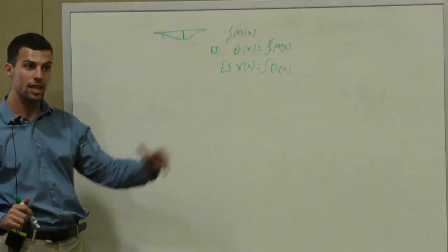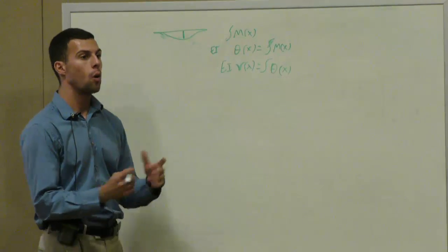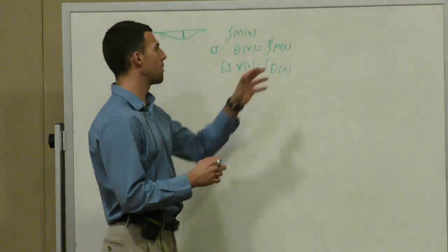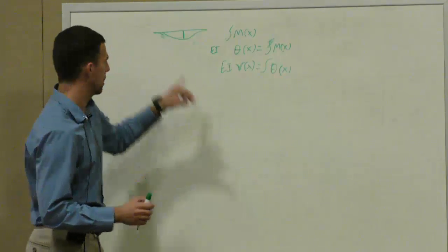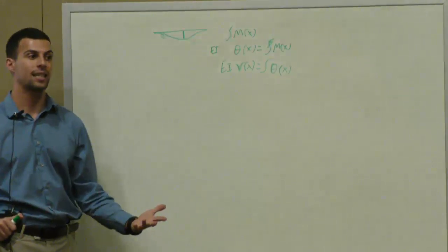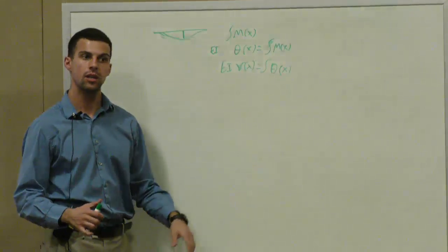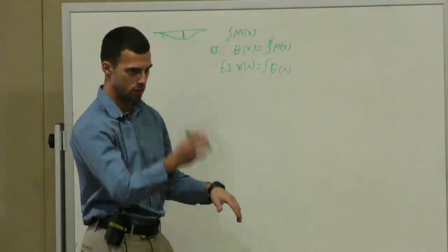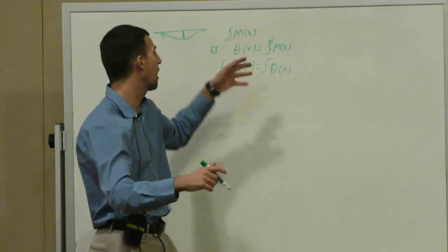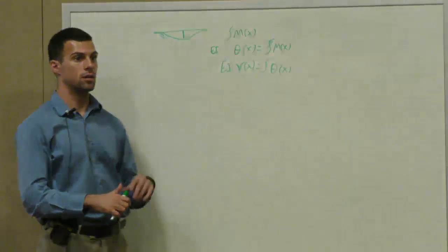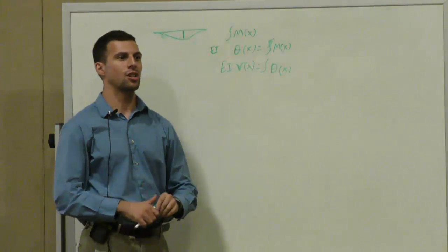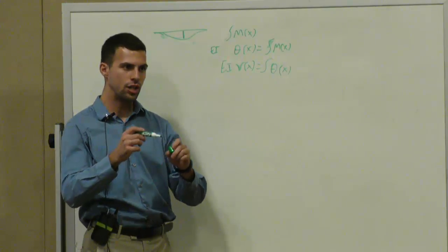So Jorge was talking about when we can do this method. This is what I like to call the successive integration method. And all you have to do is, from your knowledge of statics, find the moment equation. So you do your method of sections for however many sections you have, and you can integrate directly from that moment. Why is that not too useful, I want to say?